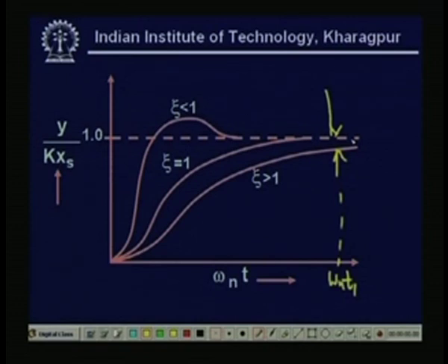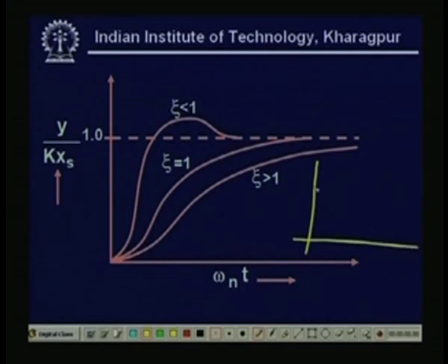We will see the definition of the settling time at the end of the lesson, because not necessarily will you always be allowed such a long time to settle down our system. Why is it important? It is also important in the case of underdamped systems, where I will get oscillation. In that case, suppose I say that when it reaches 5% of the final steady state value, you take the reading or take the action, so open the control valve, close the control valve.